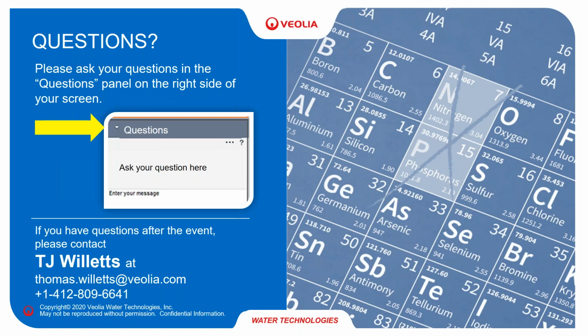If it's just the concentration that would slow down our process, we will just have to upsize the overall system size to meet the slower metabolic rates. If the concentration of salts is so high that we cannot address them, we will have to look into alternative treatments such as crystallization, evaporation, or reverse osmosis, depending on the application.